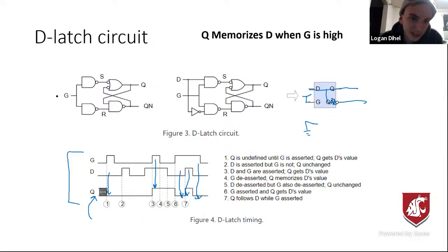So if you can see the circuit and say, hey, yep, that's a D latch, I know how they work, it's just going to memorize D when G is high. And so you just go through here, and this might be a question. I stole this off of Real Digital, but you can see that Q is whatever value it is. If you could take these two inputs right here and come up with Q on your own, then you're more than good enough for any kind of question he's going to throw at you for this sort of thing.